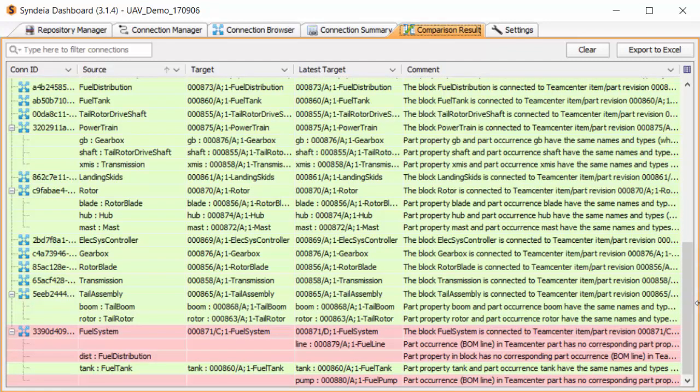In this example, we want to keep both sets of changes. We have the option of updating the SysML model from Teamcenter or the Teamcenter model from Rhapsody. There is no general solution to merging the two models, but in this case we can do two separate update operations to reach a final uniform structure in both tools that incorporates all the changes.